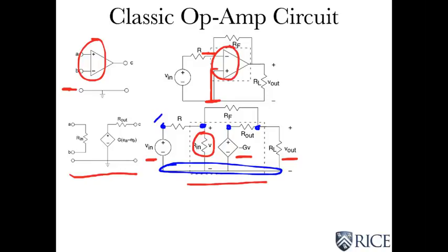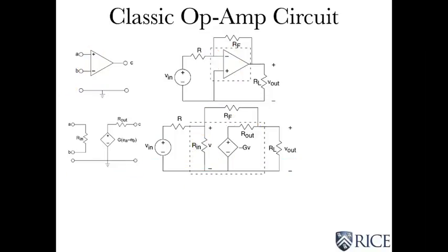It turns out the same thing applies to the dependent source, because there's a voltage source between that node and the reference. We don't need to define a node voltage. So the only voltages we need to define are V, that node voltage, and that node voltage, which turns out to be V out.